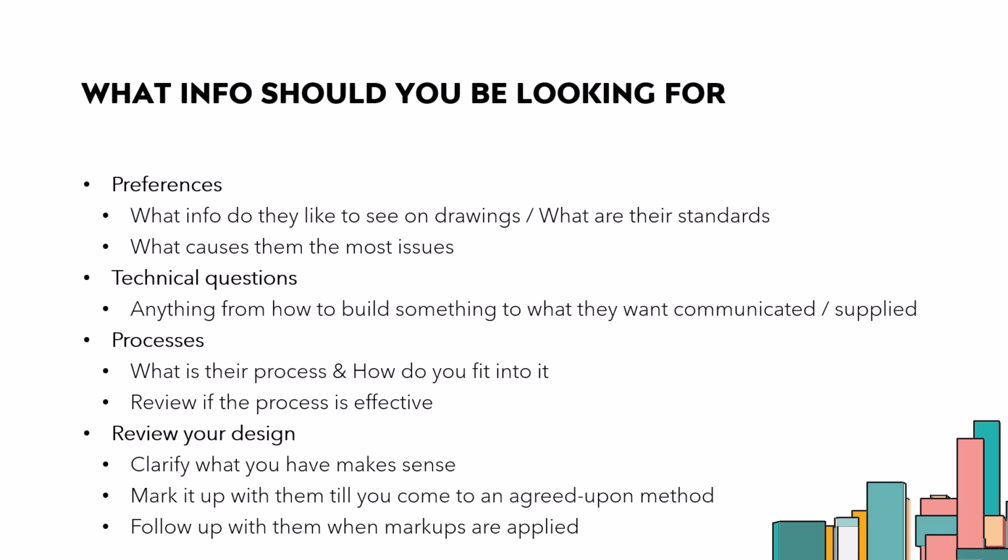What kind of info should you be looking for when you're meeting with them? Ask things like, what are your preferences? What do they like to see? What are their drawing standards? One I always like to ask is what actually causes them the most issues. Maybe there are things that they don't see on drawings, but they would really like to, that aren't part of their standards.